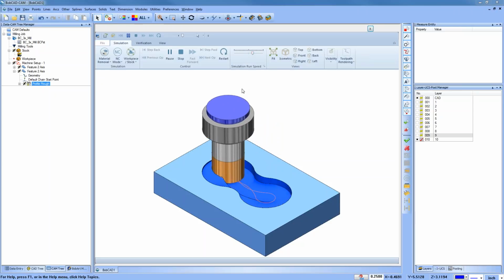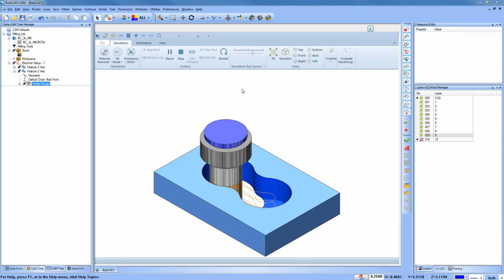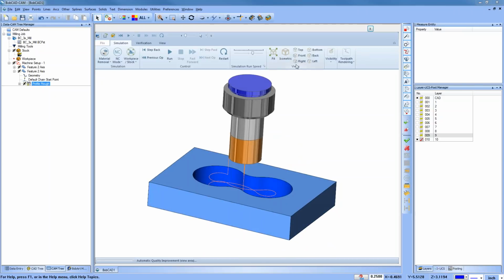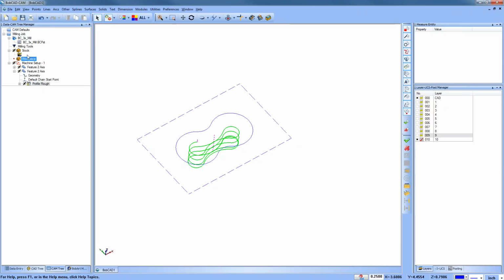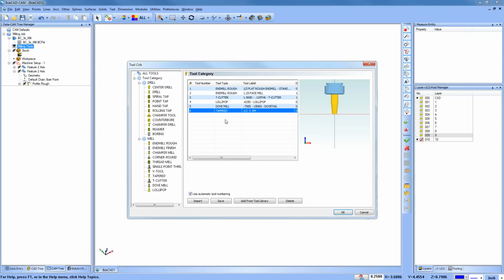But again, the takeaways for today are you have a standard profile, you have contour ramping, and you have side roughing. And there are a number of different ways that you can use those tool paths to machine different aspects of your parts. The other major takeaway is when you look at your tools, you have tapered end mills you can use for draft on your parts. You have dove mills you can use for negative drafts. You have lollipops, T cutters,